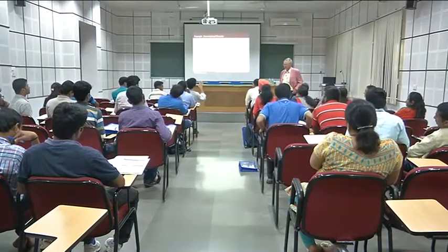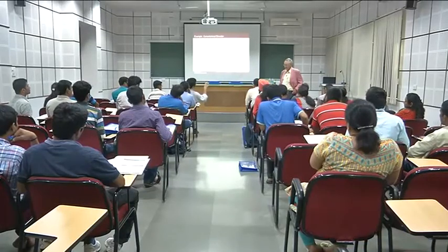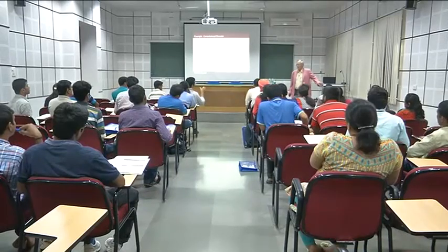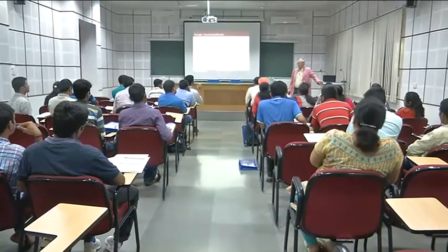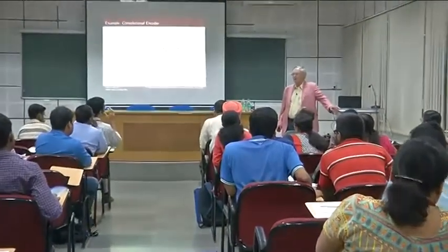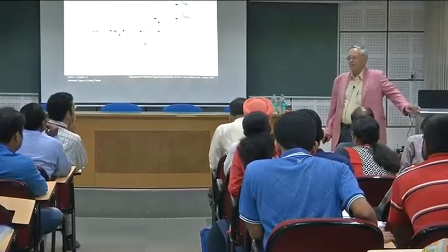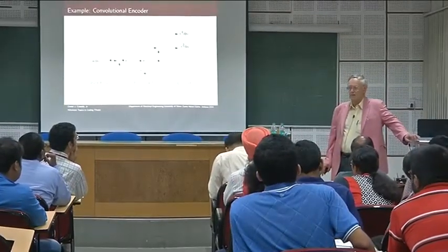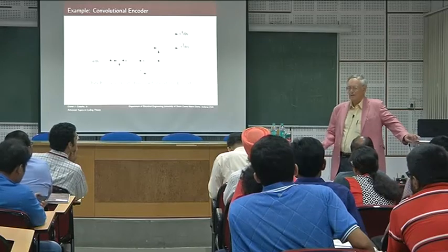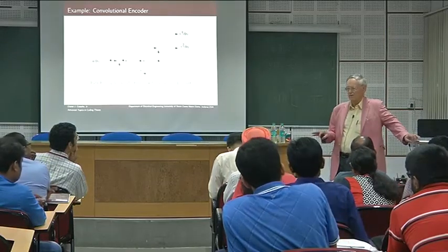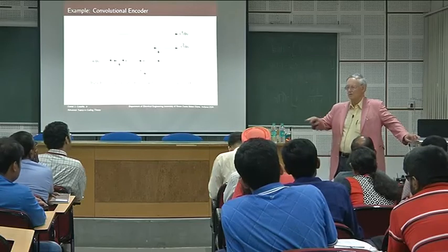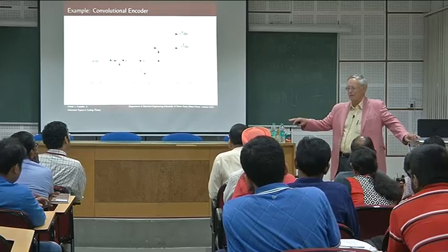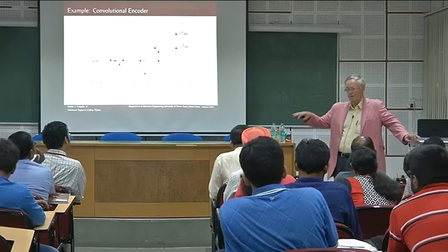Two states have to be flushed down to 0, all zeros. So how does that monitor the impact? Well, I mean, you say they have to be. Normally when you encode, it depends how you're decoding. If you're decoding using the Viterbi algorithm, which is optimum, you need to return the encoder to the all 0 state, okay? And you do that, if it's feed-forward, by putting zeros in at the end.